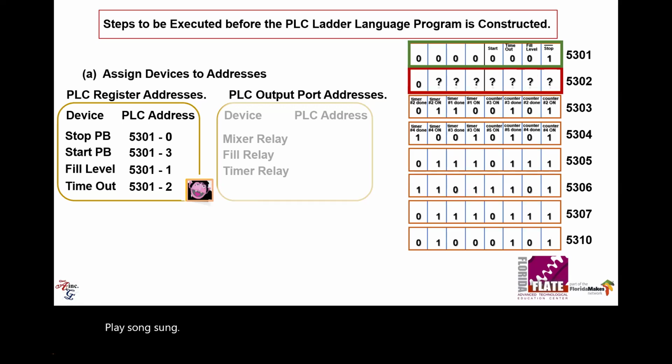So what's the hidden information here? Notice the count is smiling, because the count expected what? You should have recognized from the very beginning when you had to stare at the programmable controller, you have to find out what base it likes to count in. This one likes to count in base 8. Why do I know it's base 8? Because the last digit was a 7, and the next number was 5310.